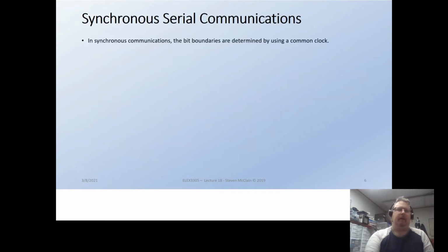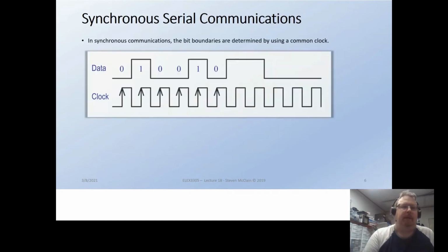Synchronous. Okay, you've got a couple of different flavors. One of them is called synchronous serial communications. In synchronous communications, you actually have 2 lines, 3 if you count ground. One of them is a clock, and one of them is the data. And what happens is, well, we'll see what happens. We'll see that